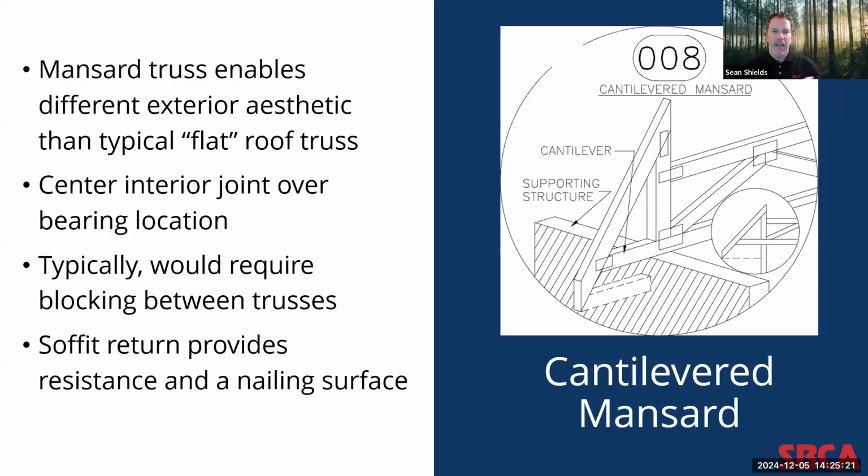So now this is detail 8. This detail incorporates several elements from past details. Now, sometimes a building designer may desire a flat pitch roof, but they want to add an architectural detail that adds an aesthetic flair to the exterior of the building and/or hides mechanicals typically installed on the roof of these types of buildings. One approach is this type of mansard truss.